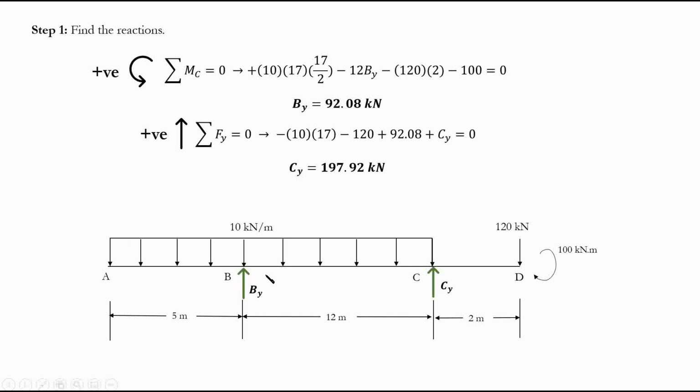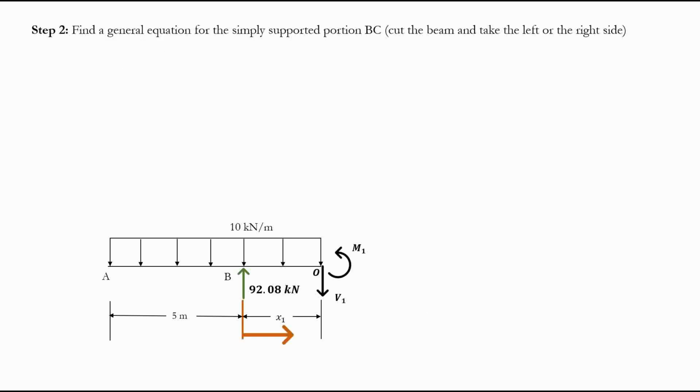So that's why, when you have a simply supported beam with overhangs and you want to find the deflection and rotation in the overhangs, you have to start from the simply supported portion anyway. Doesn't matter what the question is asking. You have to start with portion BC, from this pin and roller. That's what we always start with. You'll understand this better when we write the compatibility conditions for portion AB. But now let's start with portion BC.